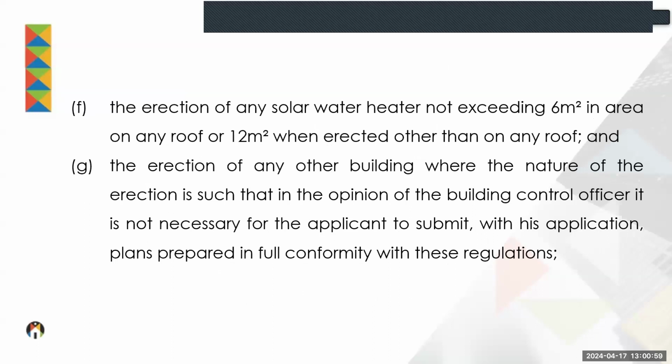the nature of the erection is such that in the opinion of the building control officer, it is not necessary for the applicant to submit with his application plans prepared in full conformity with these regulations. You might just have to do a site plan or a sketch indicating what you are going to do, and that might be okay if the building control officer decides so.